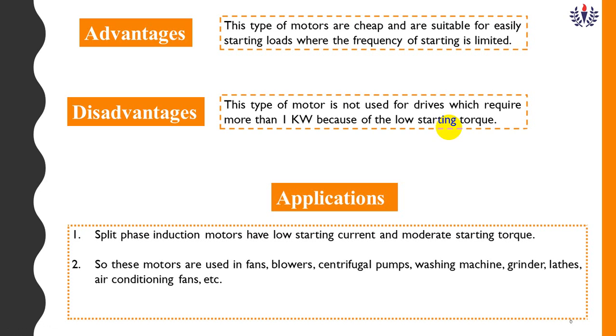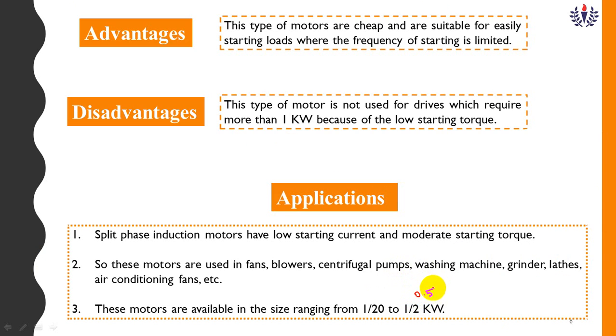Applications: since it has low starting current and moderately high starting torque, these motors are used in fans, blowers, centrifugal switches, washing machines, grinders, lathes, air conditioners, etc. It is also available in the range from 0.5 kilowatt up to 1 kilowatt. Okay, so you should understand this concept.